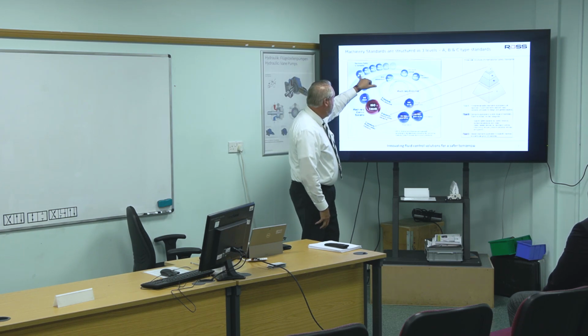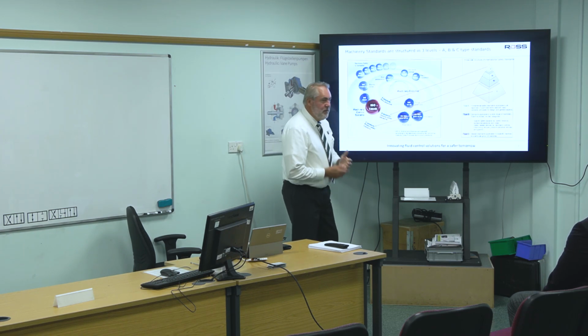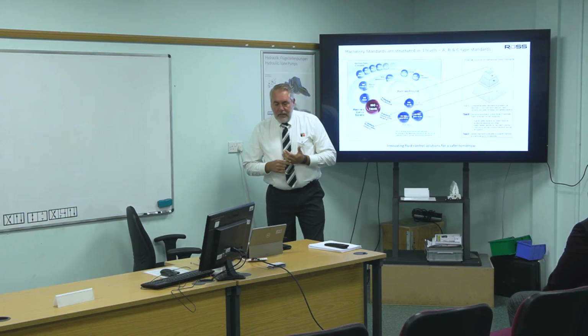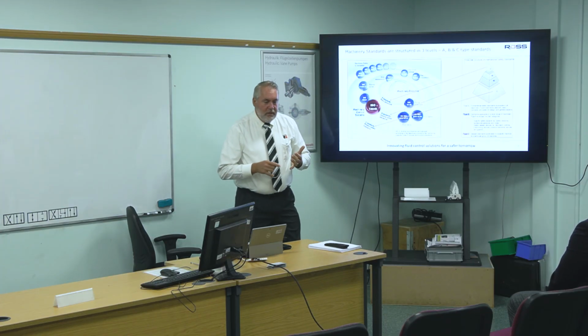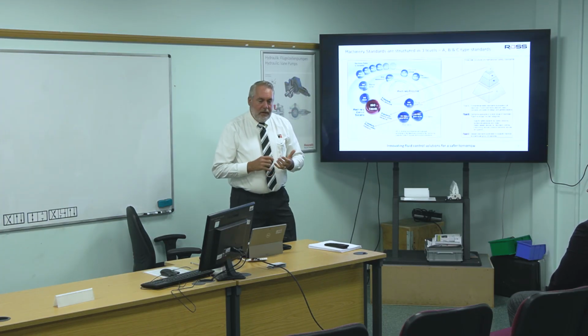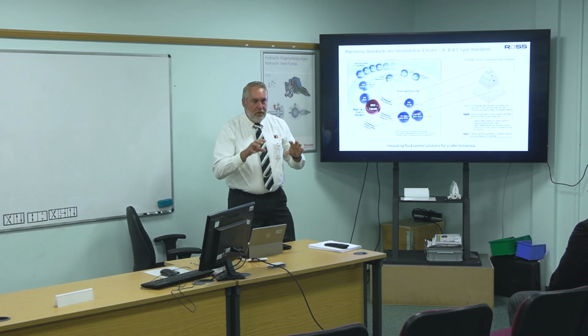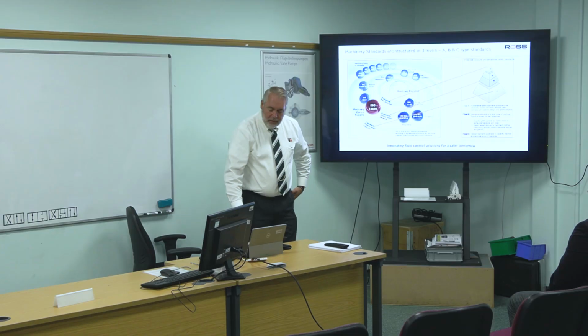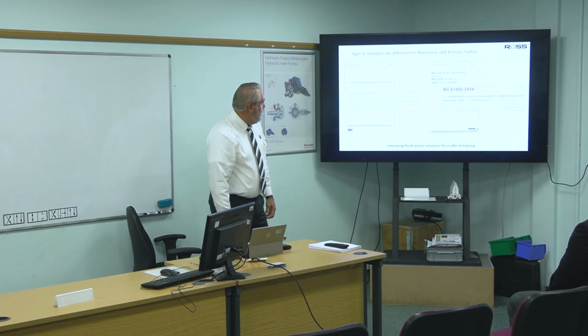You get into C standards, they're for specific machines. Like, for example, there's the ANSI RIA standard. There is ISO 10218, which is the robotic standard. You've got press standards, material handling standards, even chopper standards. And so there are C-type standards, which are specific for machine types.